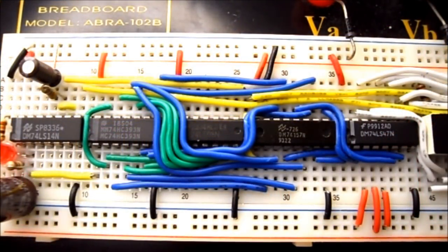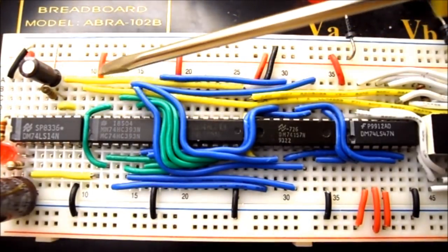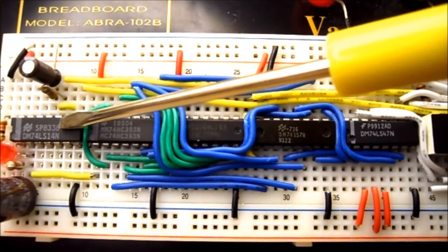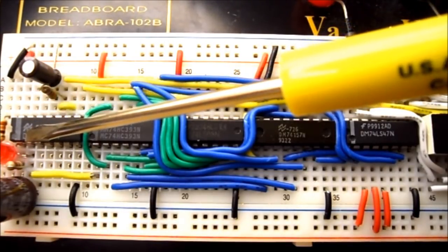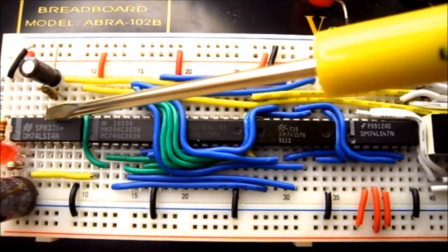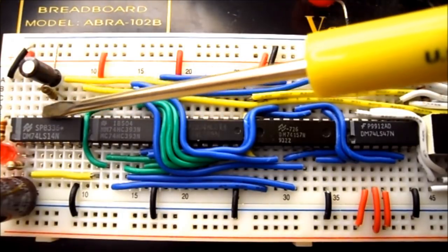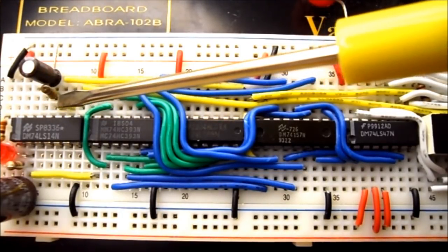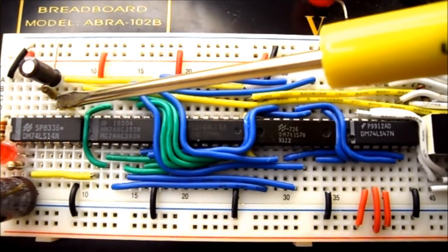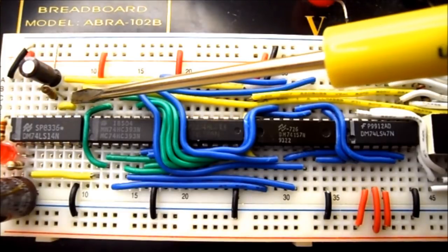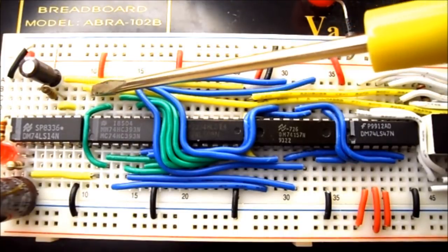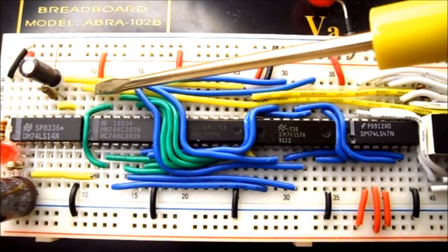So I just wanted to show you a close-up of my main circuit. You can see at this end I have my 7414, and I'm actually going to use 3 of the inverters in here. So the first inverter is for my slow clock that's running at 1 Hertz. My next inverter is for the fast clock running at 400 Hertz. The third inverter switches between the two displays. So you can see the 400 comes out, goes into an inverter, and comes out. So these two lines are selecting between the two 7-segment displays.